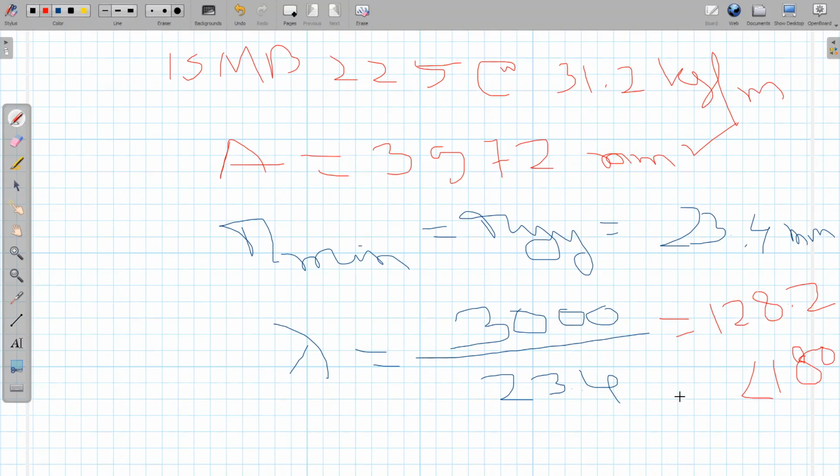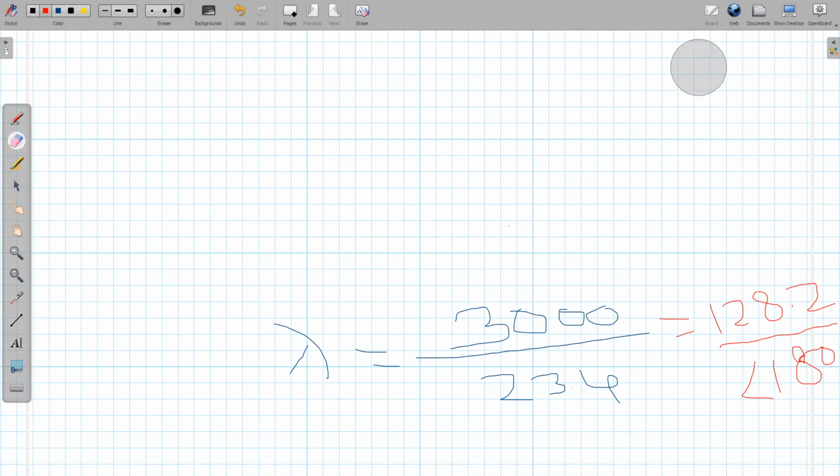Now what you have to do? Either you use the Rankine equation or the equation given in the steel table, that is sigma SC equal to 0.6 fcc fy divided by (fcc to the power n plus fy to the power n) whole to the power 1 by n, or you go to the code book, table number 5.1. For this lambda value and for an fy value of 250, you have to find the value of sigma SC, which we can easily find from there.